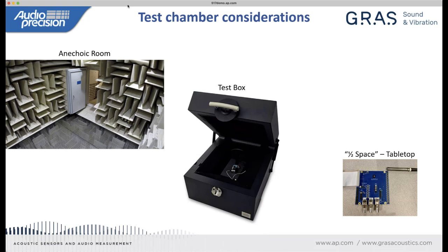And the size of the chamber is directly related to the lowest frequency you can measure. That is to say, a chamber of any given size does eventually become reflective to sound, but the bigger the chamber, the lower that frequency is. For a casual thought, if you wanted an anechoic chamber that was anechoic to 20 hertz, you'd need something on the order of at least 10 meters in size, so quite large.